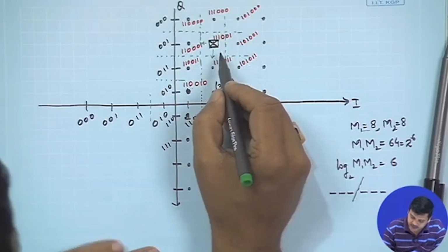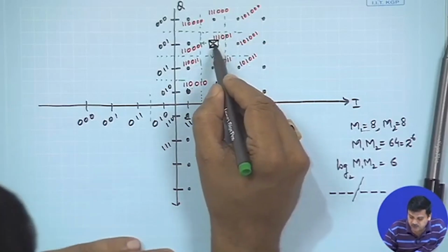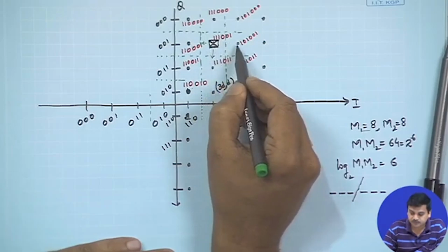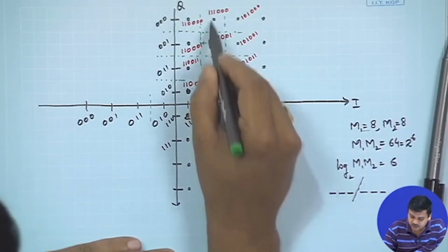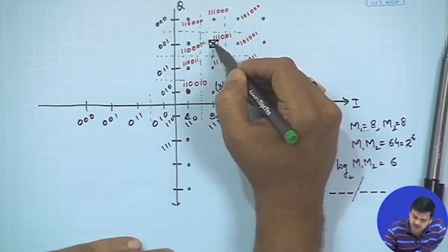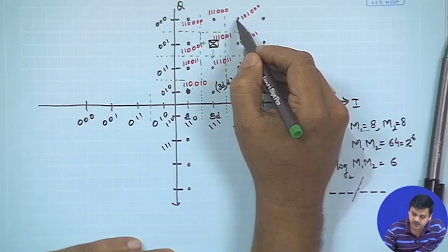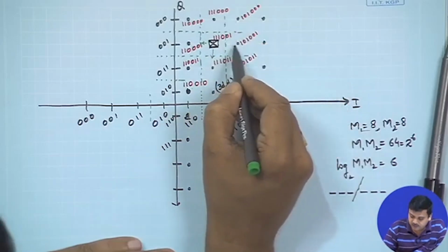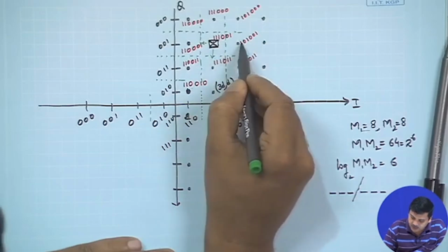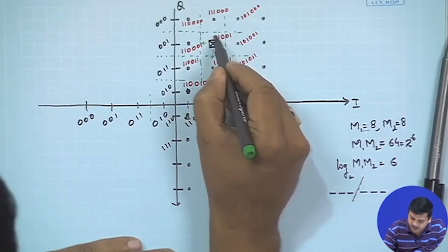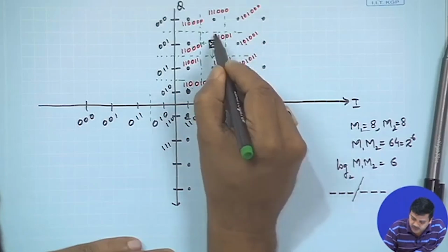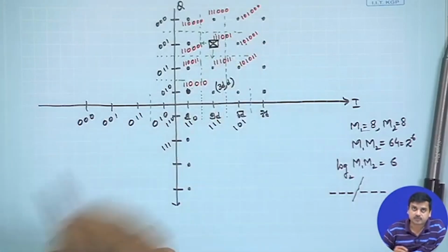Now, let us take that if because of noise the decision has been made as the neighboring symbol, right. So, these 4 are the nearest neighbors clearly by distance. This is not the nearest, but it is in the near neighborhood, right. So, if it moves there, we would find that these 2 locations differ by at most 1 bit, which is this central bit. This 0 is a 1 over here, right.